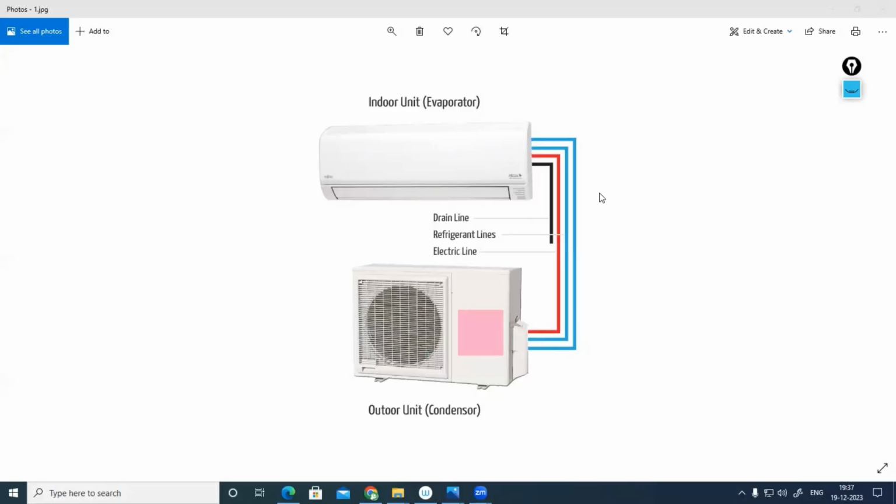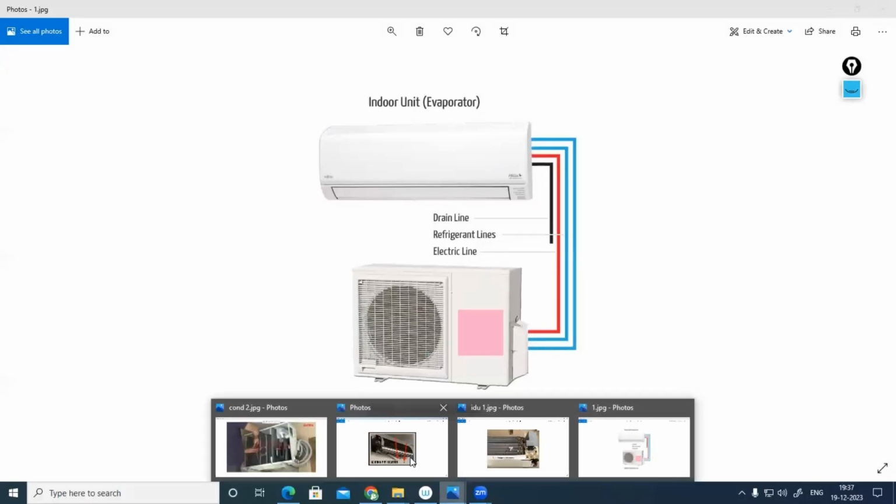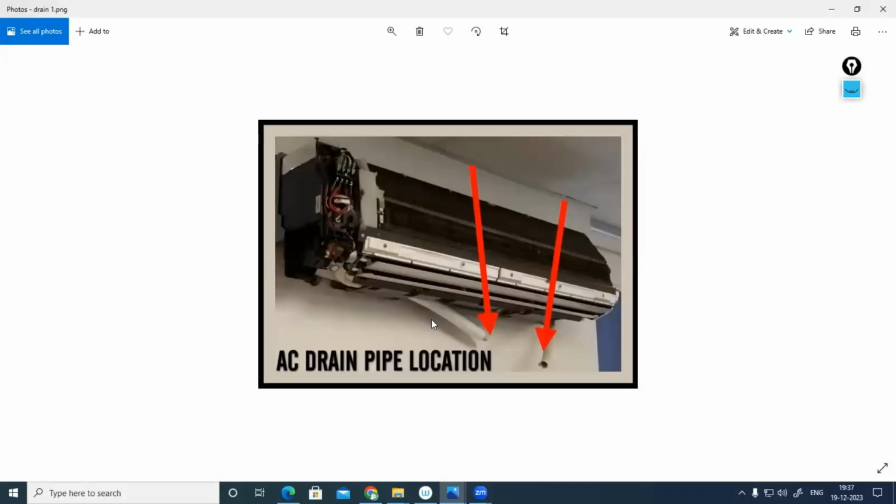So that's why in the indoor unit, there should be one more connection called the condensate drain connection. This one, just below that you can see. This will be projecting outwards, but you can hide it within the plastic cover. So we should connect this with which one? A flexible pipe or a rigid pipe. This water we have to take outside. Just below that we'll be having a condensate drain plastic tray, so water will be accumulated on the tray only. When the air is having contact with the surface, condensation will happen when it is removing the latent heat.